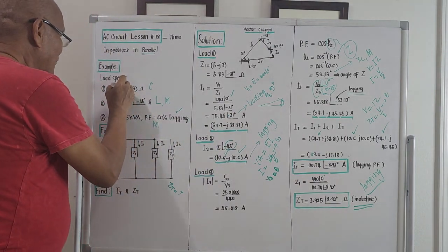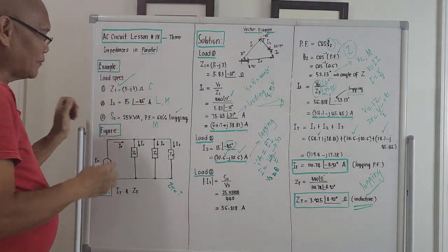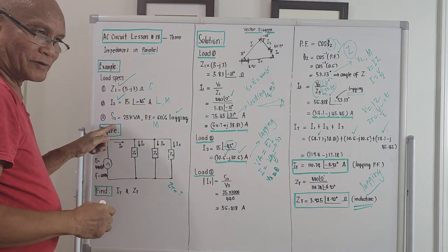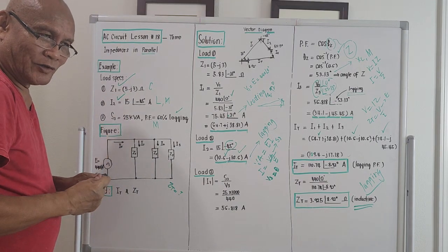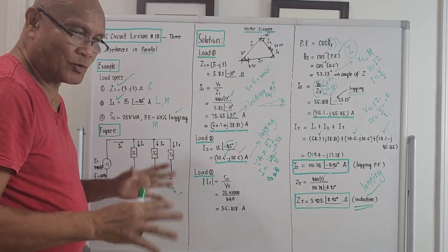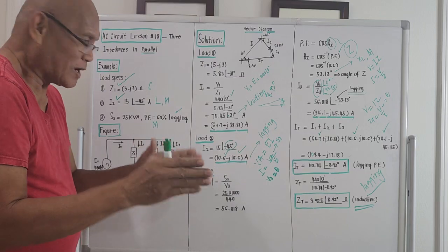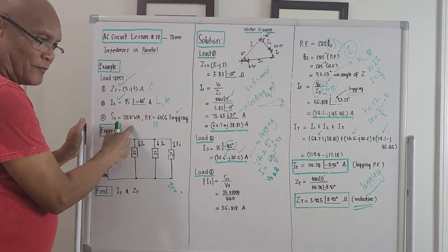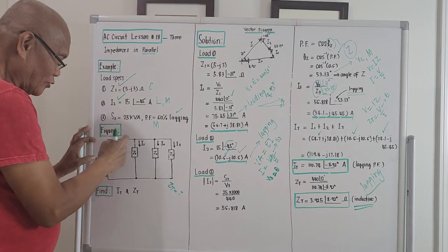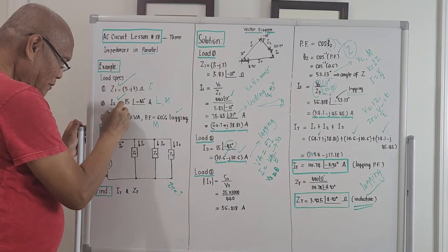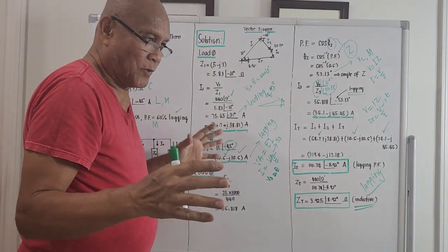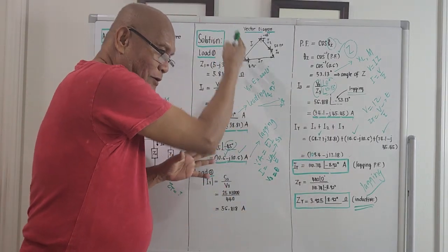If we are given the impedance, I number 2, there's no problem, the current is given. For load number 3, okay, use your knowledge on the so-called formulas. There are formulas which are needed to compute for the current, because what is given is not the current. It is the total apparent power and the applied voltage. And from this, we could compute for current number 3. And by using our knowledge of complex numbers, we add it vectorially.